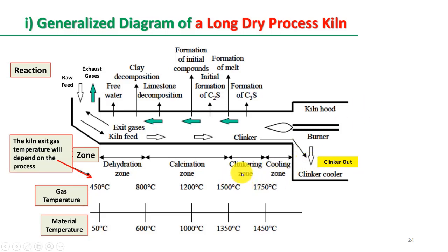After the clinker is formed, you have a cooling zone. The cooling occurs through the process of convection, so that your clinker can be cooled down. After the cooling, you will grind your clinker and add some gypsum depending upon your requirement. If you do not cool your clinker and just grind and add the gypsum, you might have a chance of a flash set and a false set in your cement. So in order to avoid that, you add the cooling zone in your furnace.